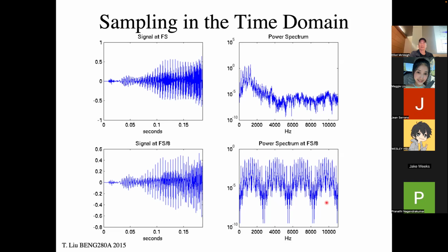This is basically a feature of the discrete Fourier transform and undersampling, which is that when I take the Fourier transform, this function is going to be periodic. And the period here is this value, whereas the period up here is actually 8 times bigger, because my sampling here was 8 times higher in frequency.